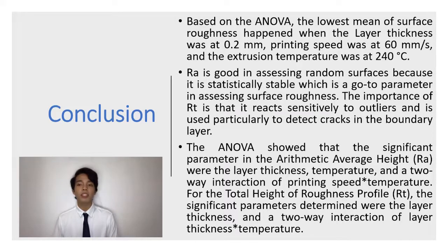The importance of RT is that it reacts sensitively to outliers and is used particularly to detect cracks in the boundary layer. The indicated surface finish parameters do not include information about the shapes, sizes of the occurrence and slopes.